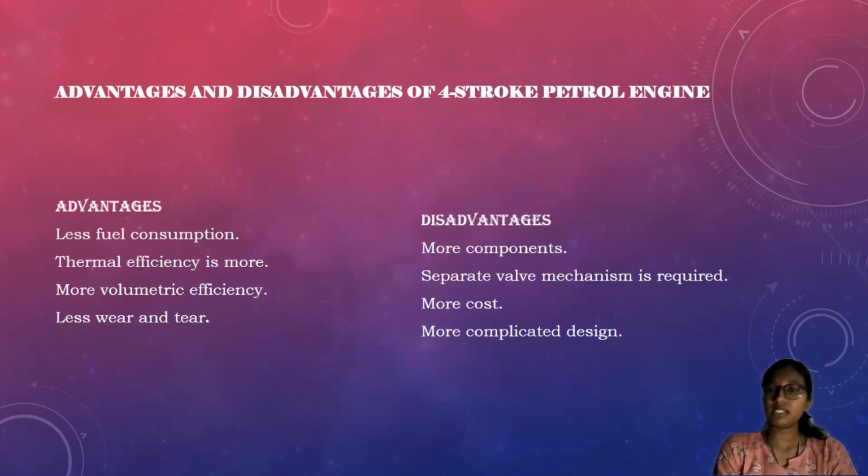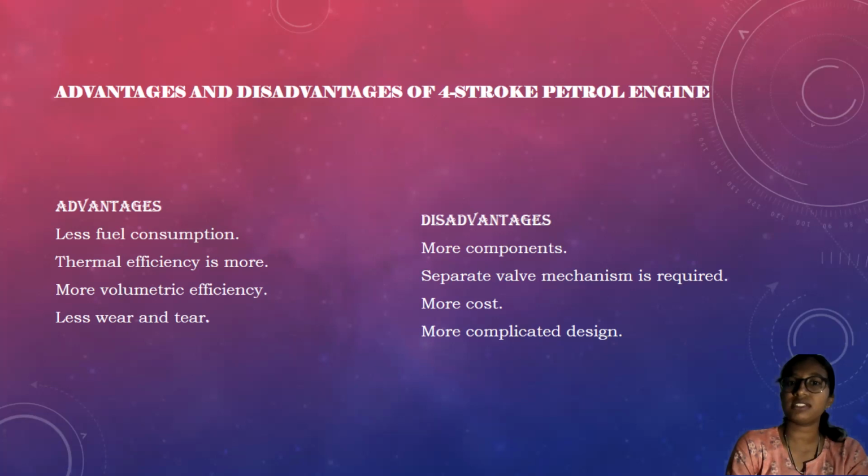What are the advantages and disadvantages of the four-stroke petrol engine? The advantages are it has more volumetric efficiency, less wear and tear, less fuel consumption, and more thermal efficiency. Coming to the disadvantages: more components, a separate valve mechanism is required, more cost, and a more complicated design.